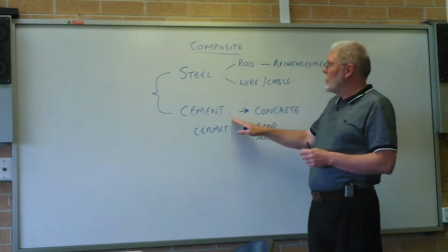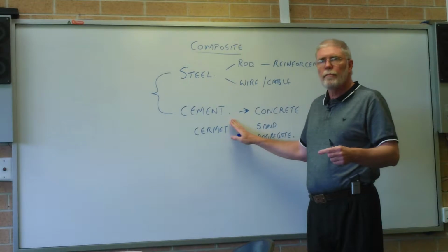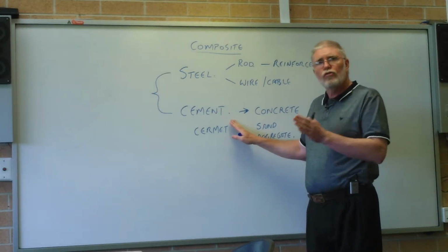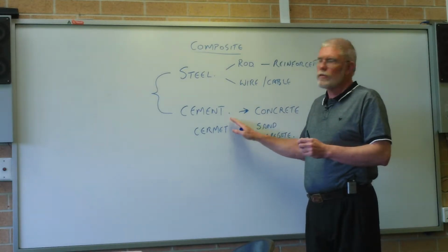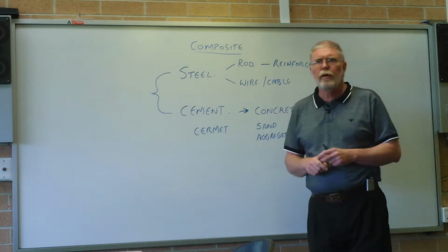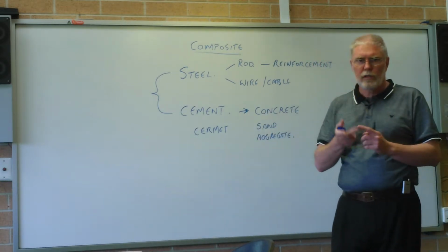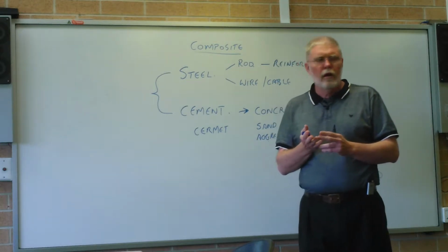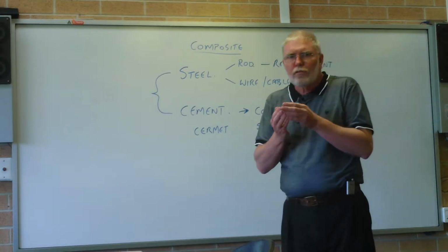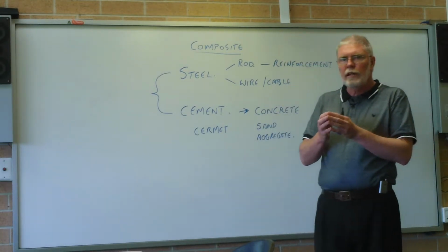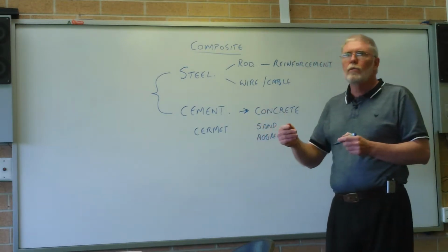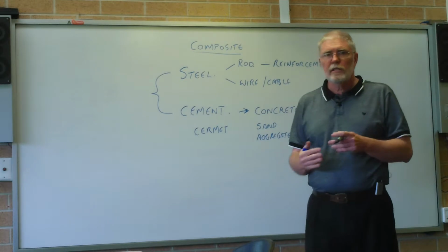And the good thing about cement is that it actually gets harder over time. The longer you leave it, the harder it becomes. And you can control the rate at which it goes off by the mixtures and the type of cements. Basically, the cement is made up of 4 oxides. Silica oxide, aluminium oxide, what's the other one? Iron oxide, silly me. So those 3 oxides are combined together with the calcium oxide, that's the CaO, which is the lime. The lime dominates.